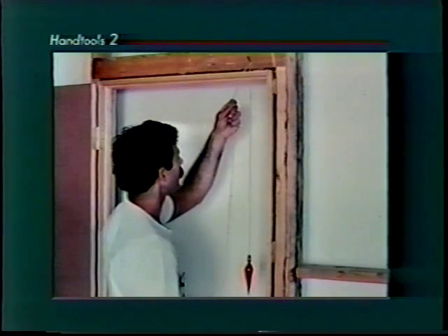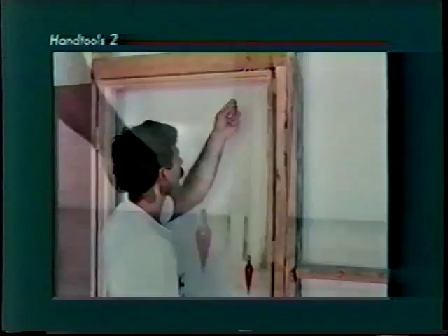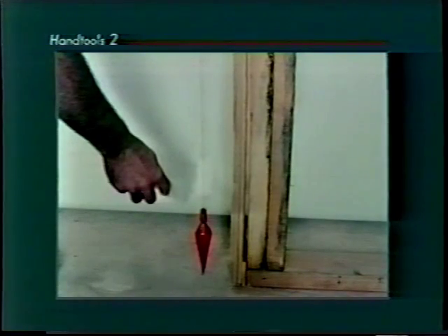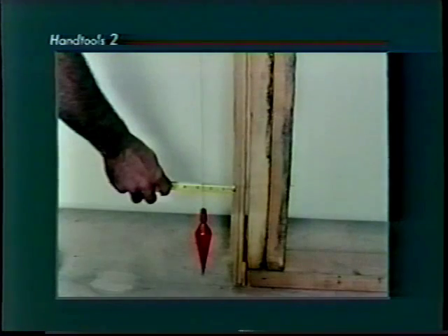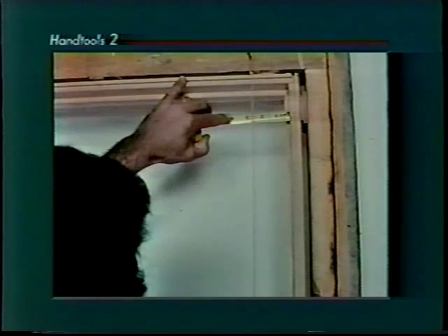Say a location or point A above is known, and point B is to be directly below point A. Secure the string of the bob to point A and suspend the bob just above the point B area. When the bob is motionless, mark exactly below the point of the bob. This line is now plumb. Now you can measure any object, such as a door frame, against the line to determine if the vertical frame is plumb.